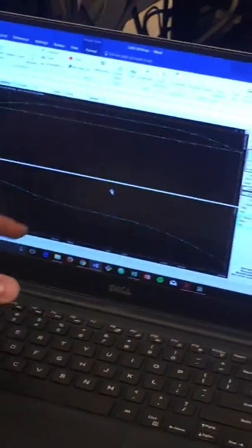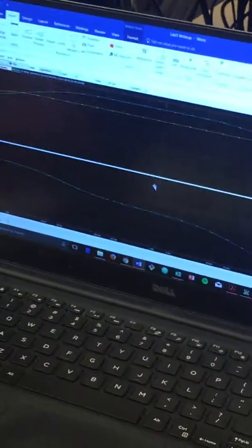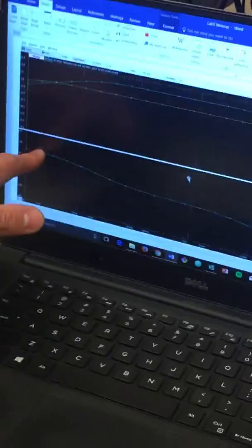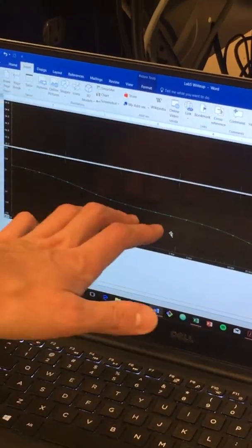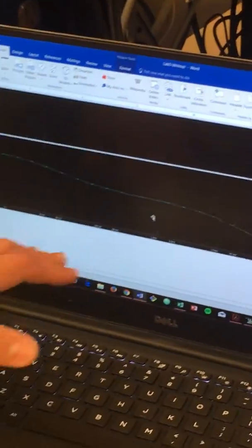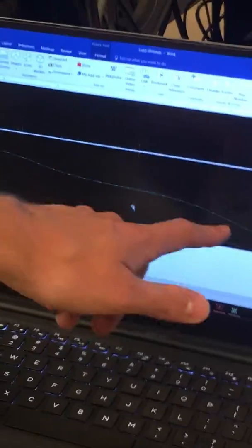And then you can see this phase response is also just an addition of the two phase responses. If you add these two phase responses from the low pass and high pass filter, you get slightly positive, but then in the middle where they directly cancel, because one was out of phase negative 180 and one was out of phase positive 180, they completely cancel and you're in phase here. And then at high frequencies it is out of phase in the negative direction.